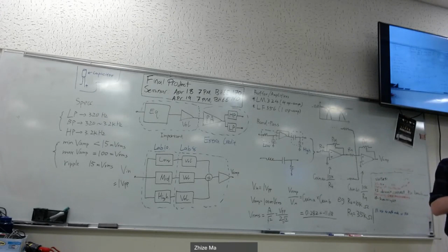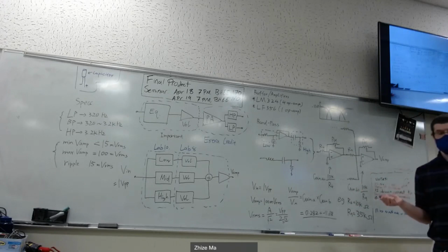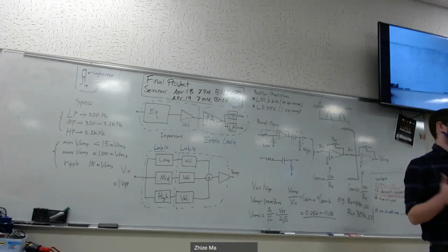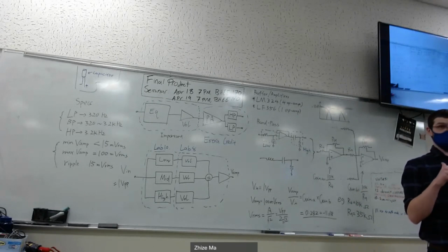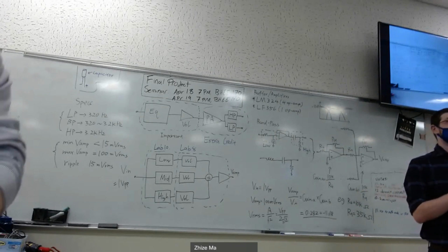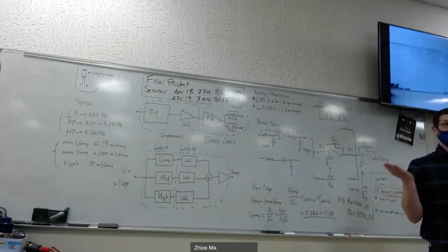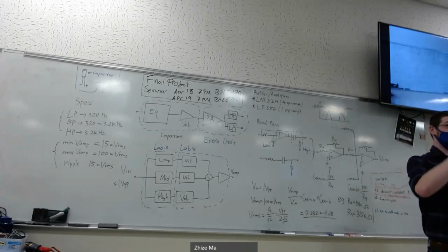The biggest things that I saw people miss last semester were the loading resistors. Pretty much isolating your equalizer from your gains from your main summing. If they don't use those, then you get this wonderful high-pitched squeal going on no matter what tone you're using. And that's due to all of your capacitors just releasing charge at random times. So making sure those loading resistors are there first off, and also not like 20 ohms, is really going to help with that.